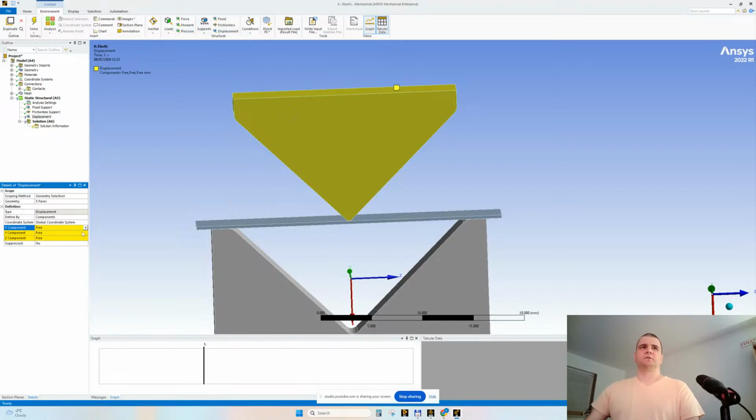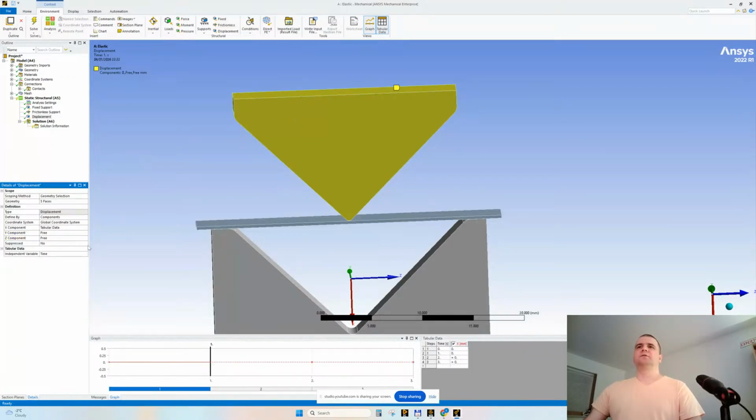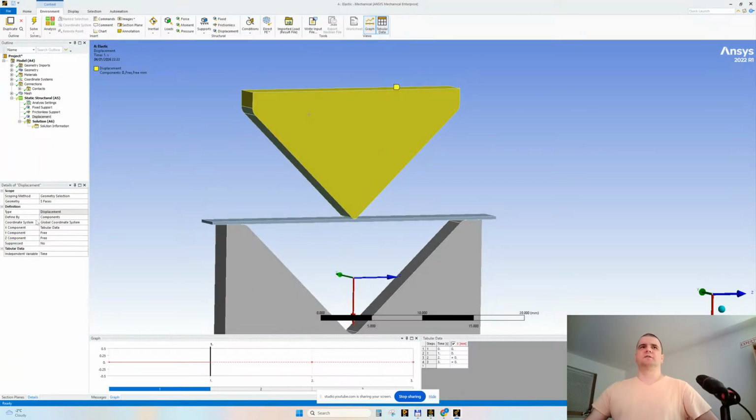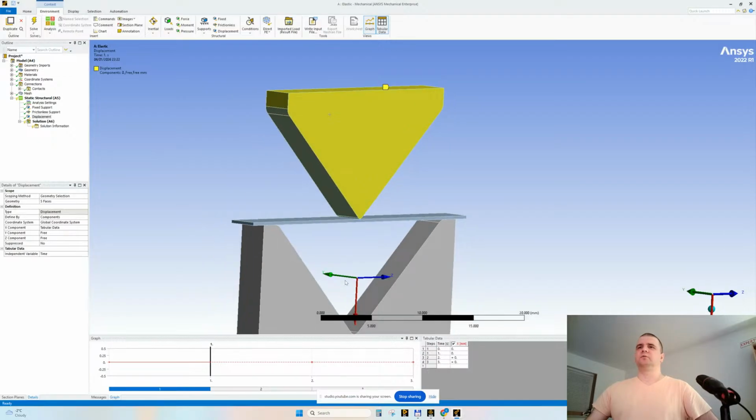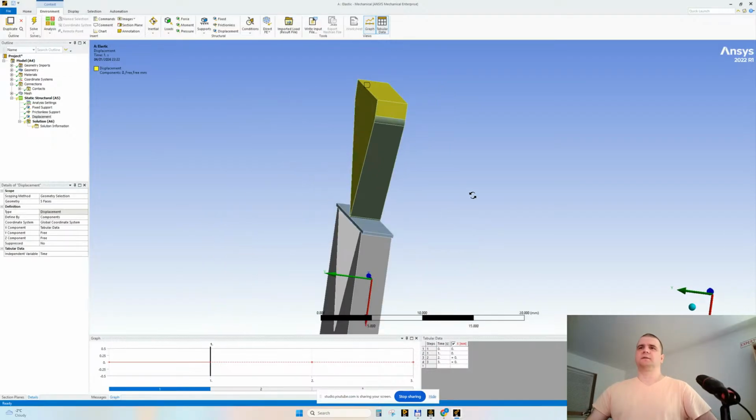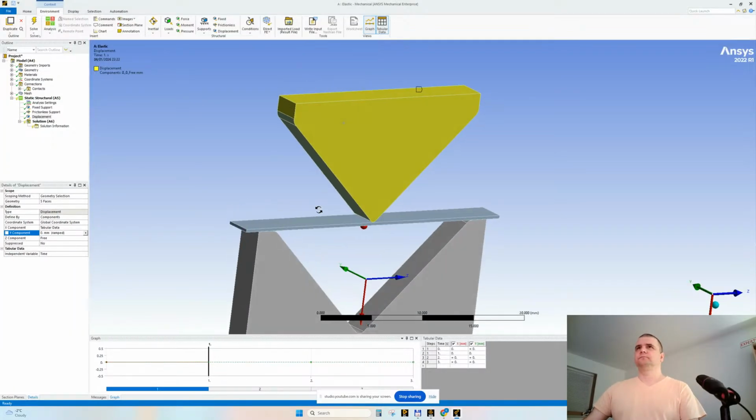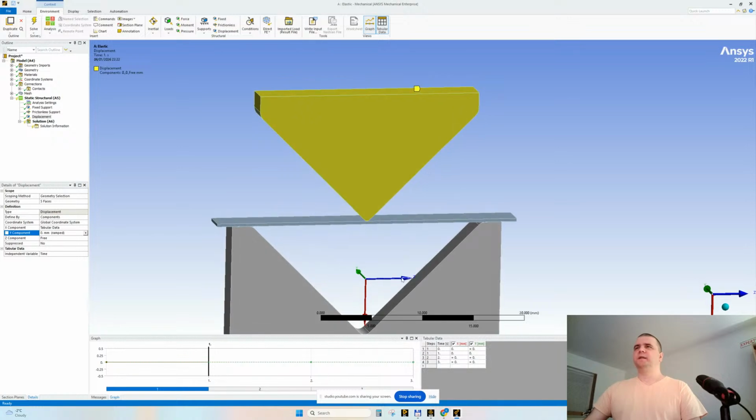The displacement should be, of course, about the x-axis, and we select here tabular. In order to remove some degrees of freedom, we are going to select 0 for the y-axis, yes? Let's make it 0. Do we need the z displacement? No, we don't need it. Let's make it 0. This will help the solver very much. It will be much quicker.